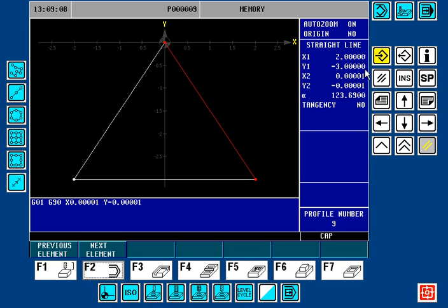If you remember from our previous examples that we talked about in the error in data, we talked about sometimes being off on the 5th place decimal just by 1/100,000th of an inch is enough to error out in the profile editor with incomplete profile data. Here, this is resulting in an error that says that this shape is not closed.